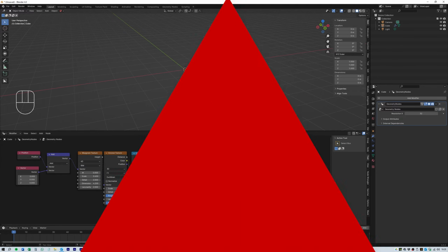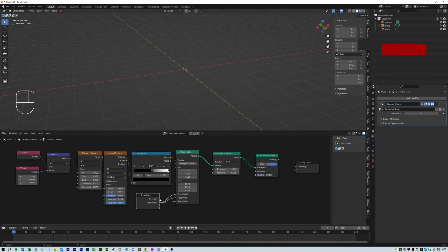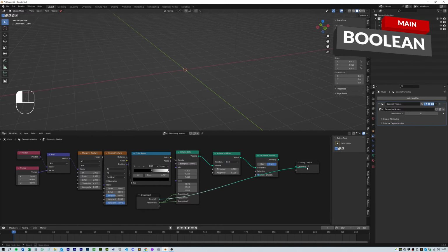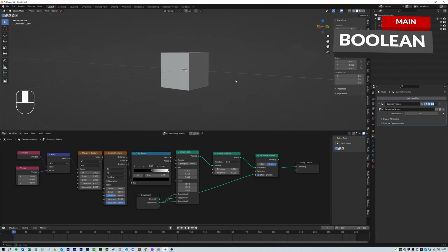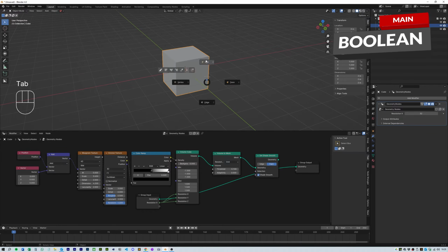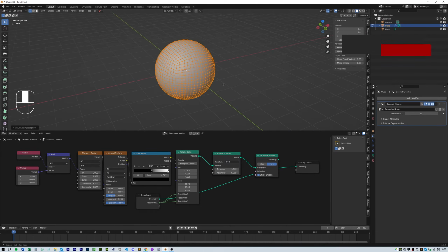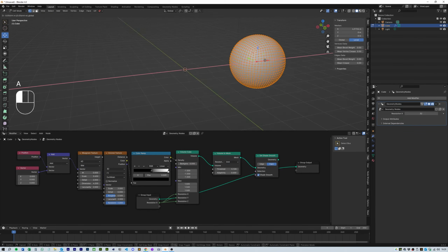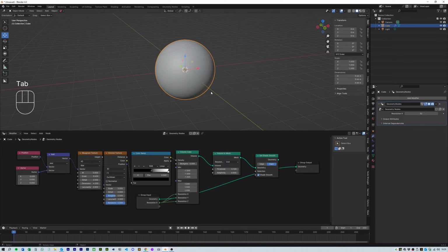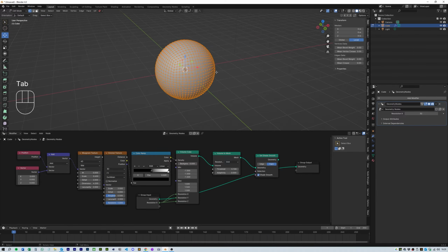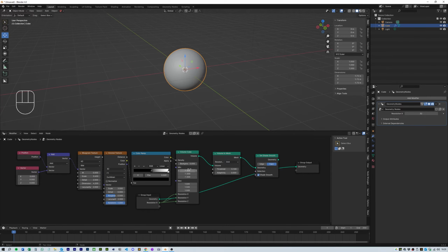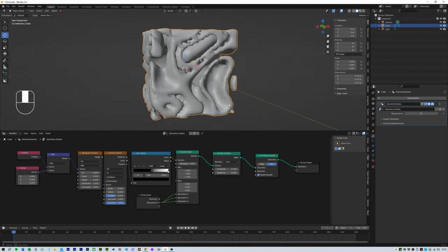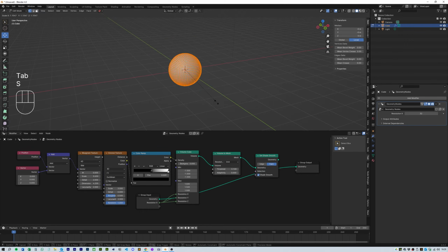First up, I'll show you what it's like to actually change the geometry input in the geometry node. So to do that, we're going to connect the geometry and you'll see that the square comes back. Go into edit mode and add a sphere. Move this off to one side and then delete the cube. Then you can select this again and move it back to the center. What you need to do now is make sure that the sphere is smaller than the volume cube that you've set. You can do this by staying in edit mode, then connecting the cube, and you'll see that you can see the outline of the sphere within the cube.